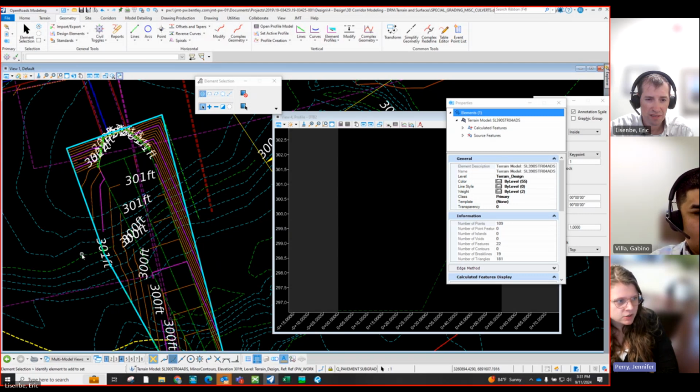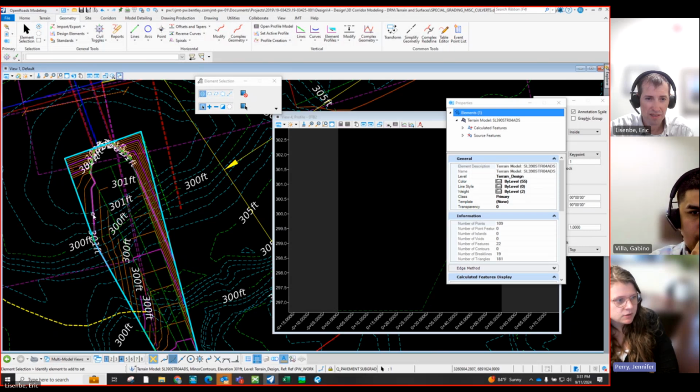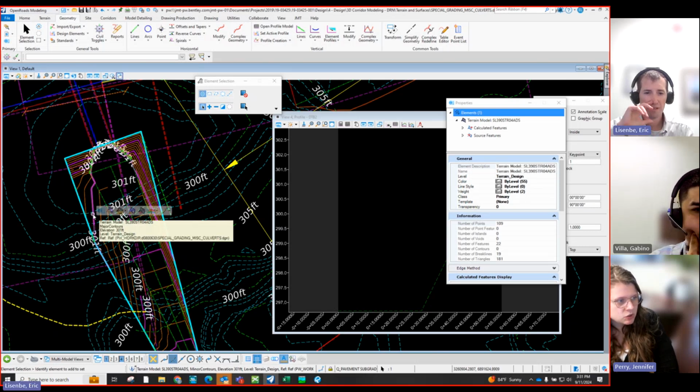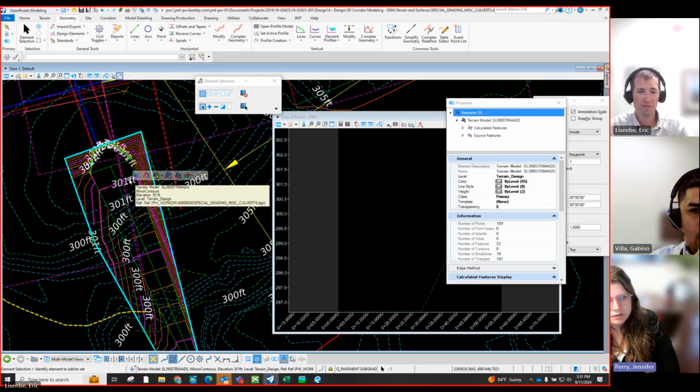That's what we did for the bridge, because with the bridge grading, well, even culvert grading, you can make it smooth if you're just doing it by hand. For some reason there's a disconnect with the modeling to do that, and it's harder sometimes. And they took away the tools to be able to do it completely by hand. We used to cut a cross section, see where those elevations hit, and then use active chain control to draw the elevations from the cross section to the plan view.